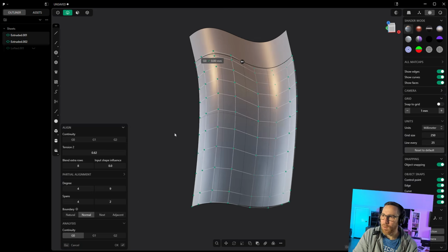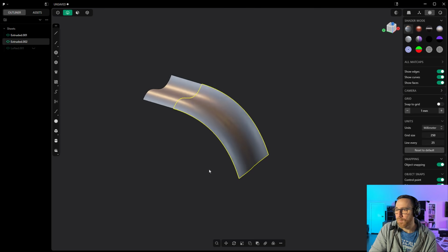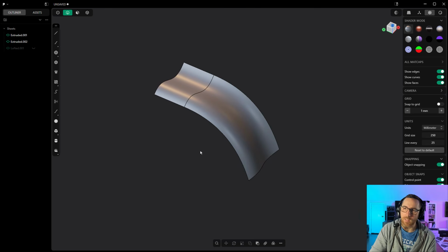And so overall, that is what we have for these XNurbs tools. And that's, again, square and the align tool. The align is going to be somewhat of a sacrificial tool. That original surface goes away, whereas the loft tool and the square tool are very similar in nature. Square tool giving you more influence over those internal CVs and how that surface is shaping up. The loft tool is just going to allow you to do things like the tension or the tangency influence, as well as the tangency type, G0, G1, G2.